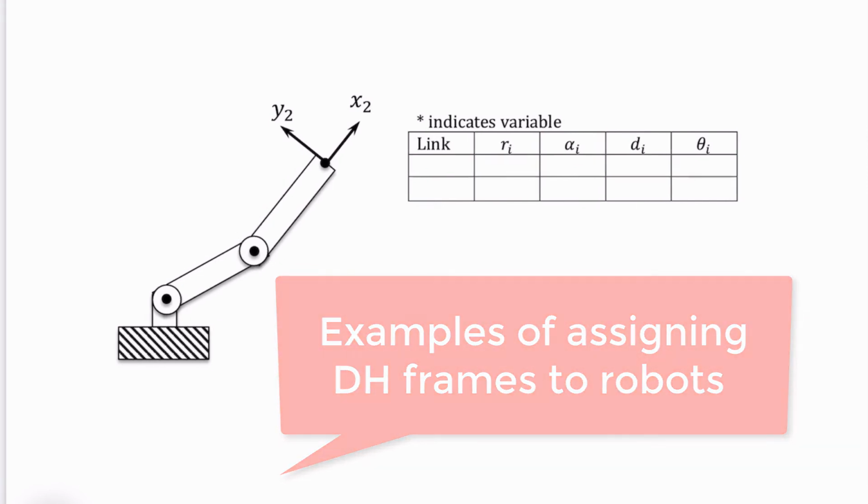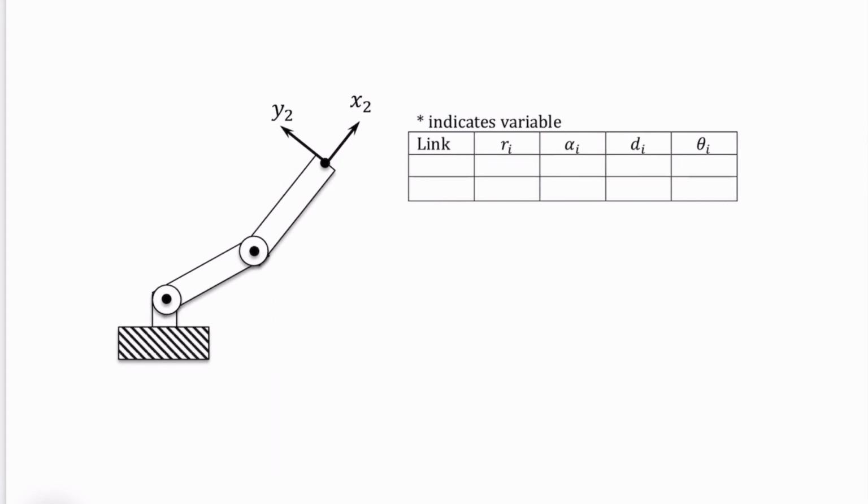So now it is time to do an example. Somebody hands you this robot, and we want to apply all of our steps and see where we go. Step one is we need to label all the axes. My axes, these are revolute. So these axes have to be right on these joints that are revolving. This one is straight out of the page.